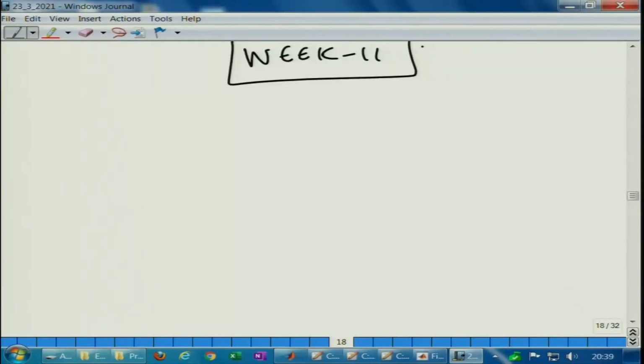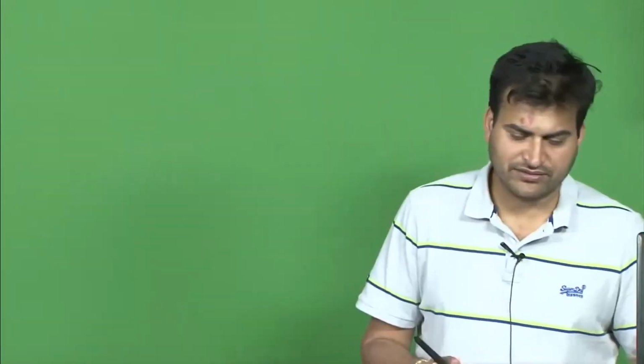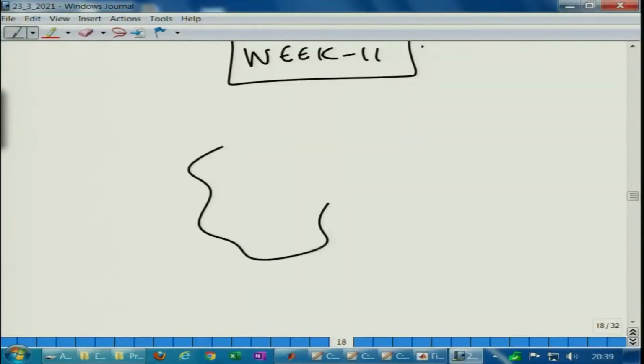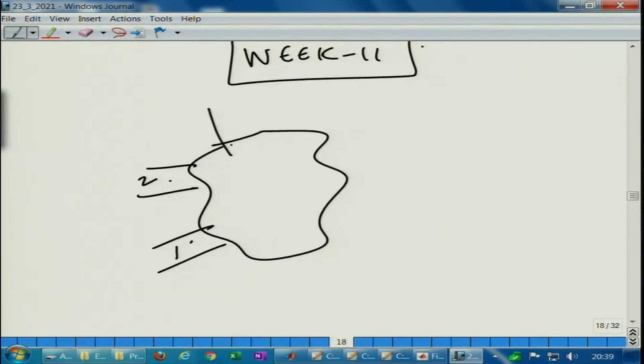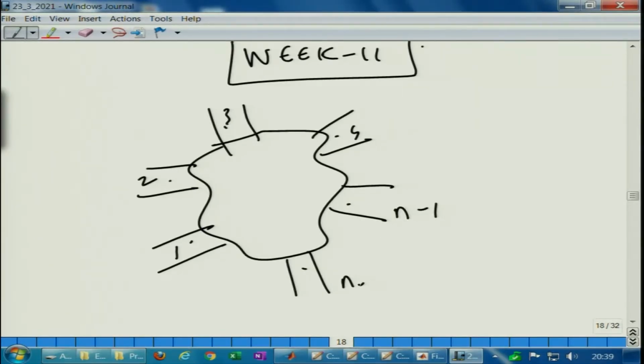the way we are going to characterize this system is using the impedance matrix, which is basically nothing but the transfer function. So, let us say you have an arbitrary muffler, and you have, say, the first port 1, 2, 3, 4, 5 and say 6. Okay. Let us say we have 6 ports. Instead of calling it 5 or 6, I would say n minus 1 and nth port. So, how do you characterize such a system?